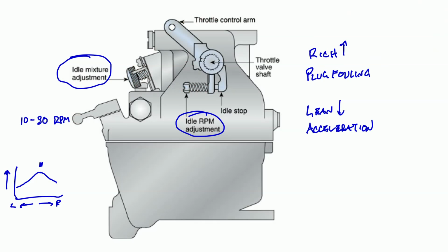If we get a huge jump in RPM, it means we were way too rich. And so there's a big difference between where our idle setting was and where that stoichiometric value was. Conversely, if we pull the mixture and we don't see a rise at all, that tells us we were either right at stoichiometric or we were on the lean side of the curve, and so it just died off. It didn't go through that extra amount of power before it died.